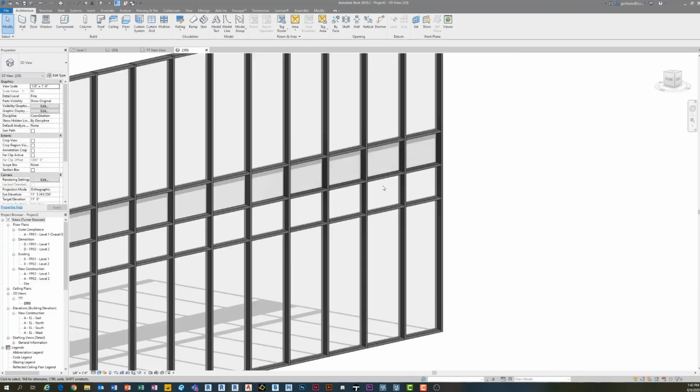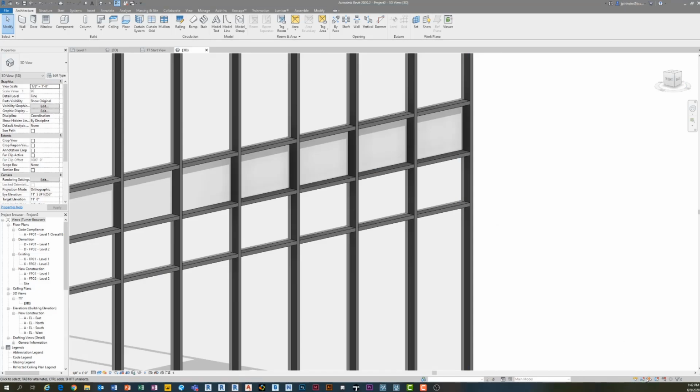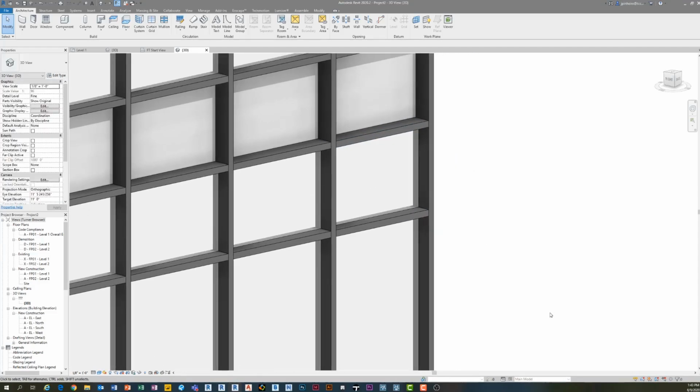Now the reason, Jerry, you may not be able to select something is because down on the bottom right hand side there's this little area that Revit keeps sneaking little things into, and it is good because to some extent, depending on the model you're working on, it's nice to have the ability to turn these on and off. But these are actually selection settings. So you can see here it says select links. So if I click this button, now there's a red X there, I wouldn't be able to physically select a Revit link, which, as you can imagine, can be helpful if you keep dragging across and selecting things.